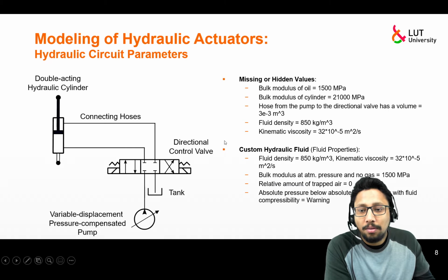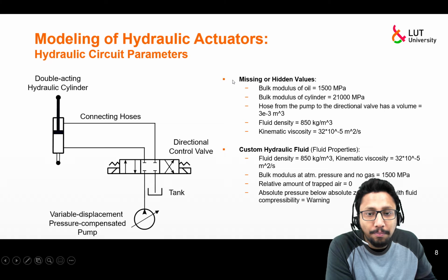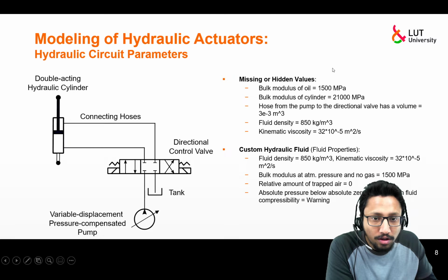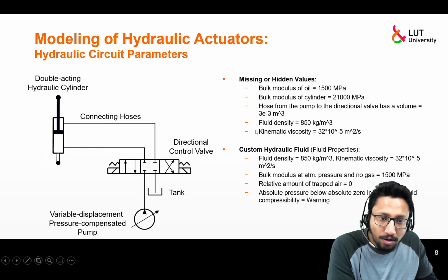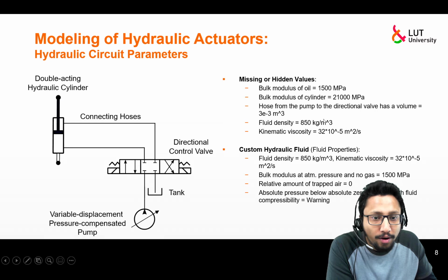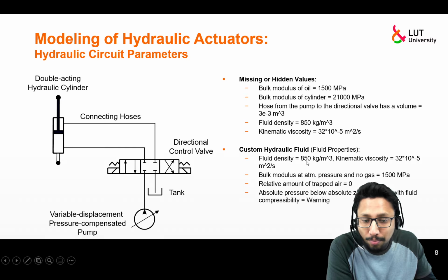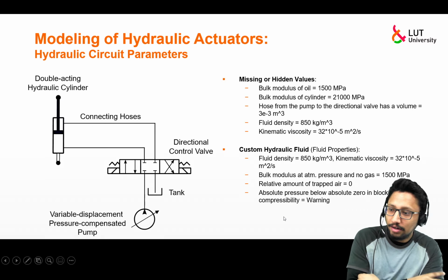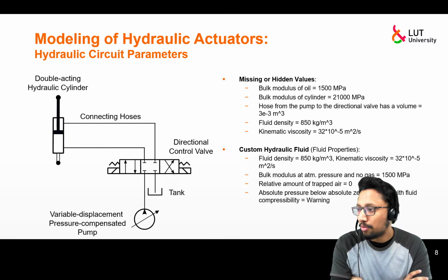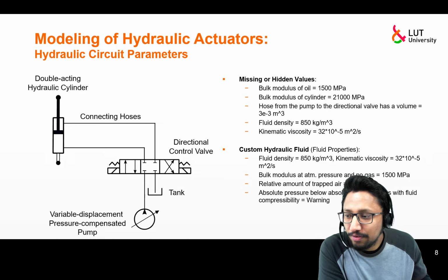Good. But there are some other parameters which might not be provided to you in the simulation work, but I have included them in my presentation and in my video. So there are some missing values, for example the bulk modulus of oil, the bulk modulus of the hydraulic cylinder, the fluid density, kinematic viscosity, or how you can model the fluid properties in Simscape Multibody. So you can find this information useful. If you know how to model them from tutorial 6 and 7, it would be very easy.